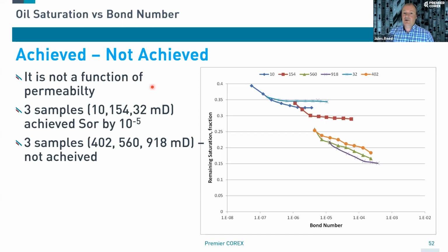And centrifuge is not going to be good, because what the centrifuge will do with the gas for an imbibition is compress the gas into the center of the sample during the testing, when you're applying a force, and it appears as though you're having change. But as you stop the test, the gas will expand again, pushing the fluids out. So you get a disparity between what's happening when, and you could be just dissolving gas rather than displacing or moving gas. So a centrifuge is not recommended for those. Flooding is better.